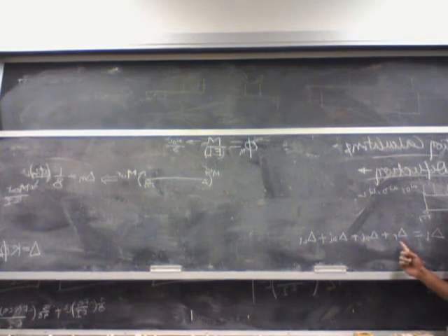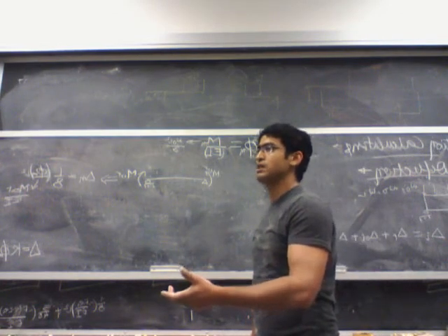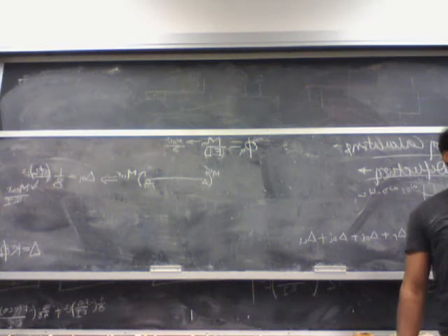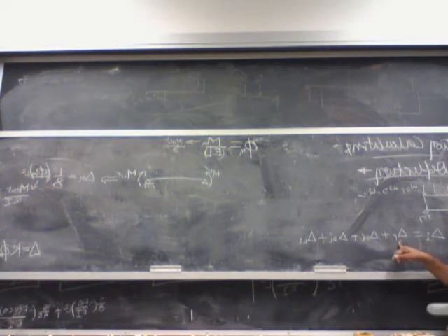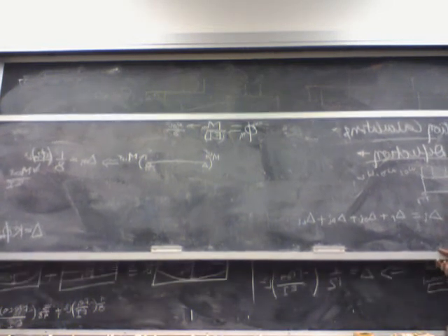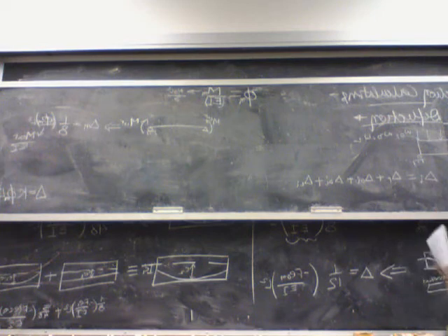Now the question is whether I use Fi or the effective prestressing force when calculating this deflection due to the prestressing strand. That depends on the problem statement. The problem statement will tell you whether to find the instantaneous deflection right after stress transfer. In that case, your prestressing force is Fi. If it says find the instantaneous deflection at service condition, or when the prestressing force is the effective prestressing force, this will be based on F, that is eta times Fi. So the problem statement will tell you whether to use Fi or F for delta P. And then depending on what kind of strand profile you have, you will use either of these three factors to actually find your deflection. Okay, so this is the instantaneous deflection.